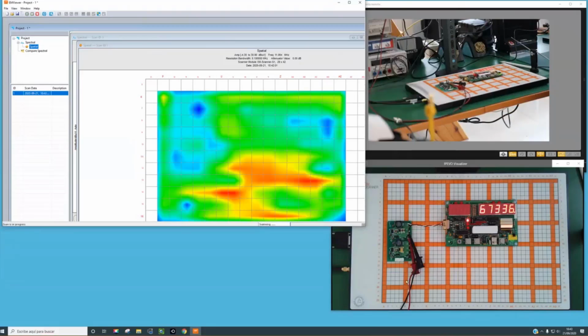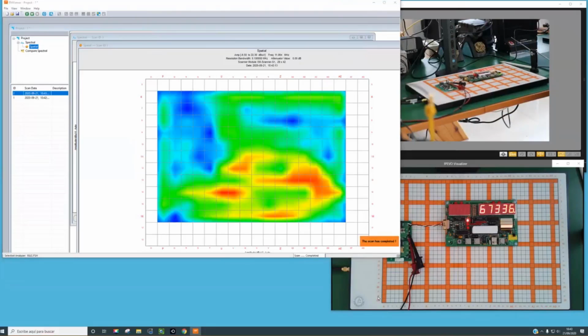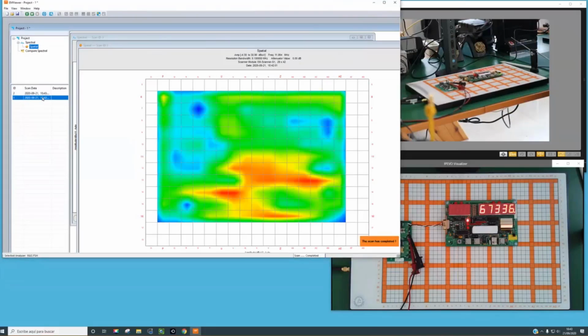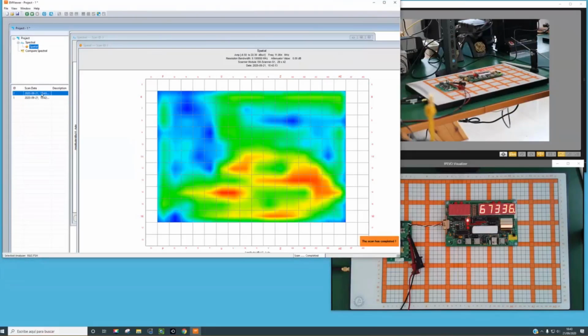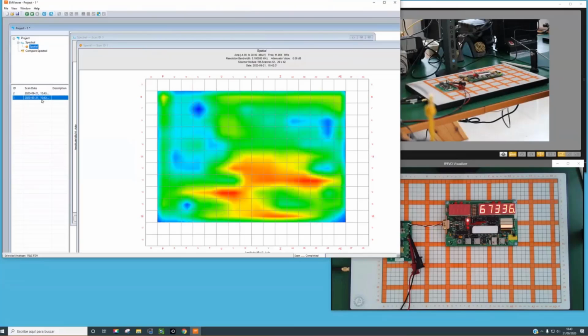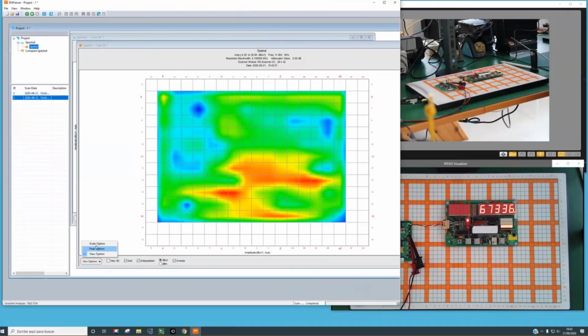They look similar, but by default the scale is automatic. So let's go to the scale option and specify a specific limit, for example from -5 to 30. This is without the change. Now let's go to the second and specify from -5 to 30.